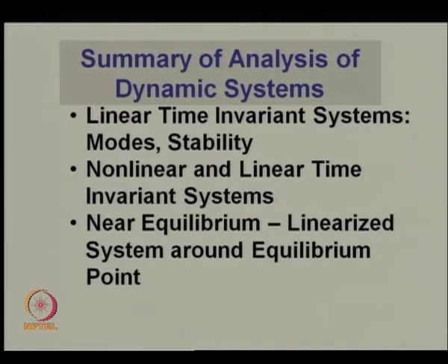We considered linear time invariant systems and we could characterize the response in terms of modes. We could even understand the stability of such systems simply by looking at the properties of the A matrix. In particular, modes could be characterized by the eigenvalues and the eigenvectors associated with the A matrix of the system.